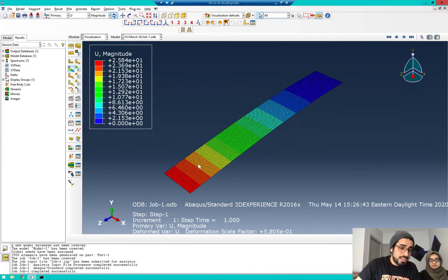Okay, and we don't have any stress concentration problem because all of them have the same deformation. If we had a stress concentration problem here, we might have much more displacement. The contour would show different colors, and here it would have stress concentration, which means we have more displacement. So we don't have that problem here. The deformations are really nice. You see the contours, how they are, which means we don't have stress concentration here.